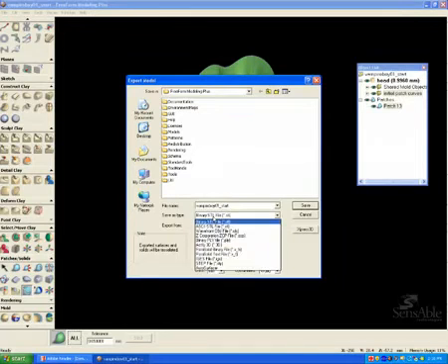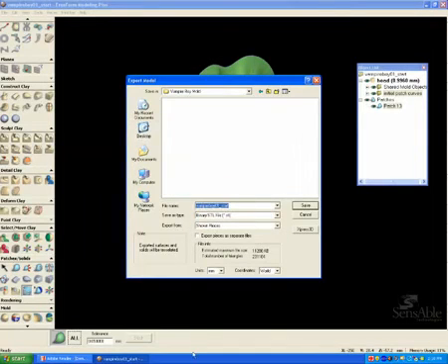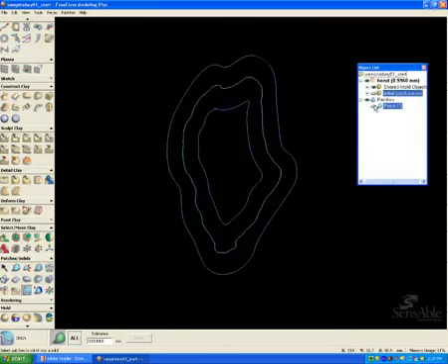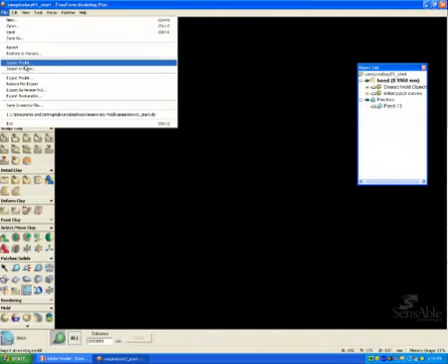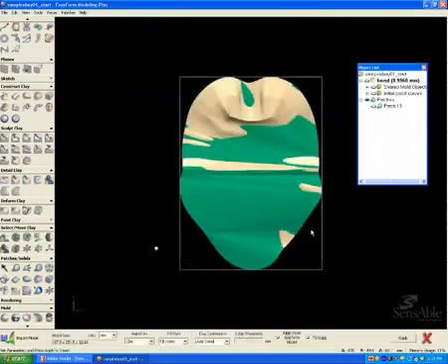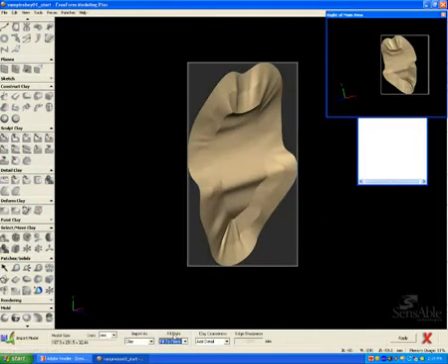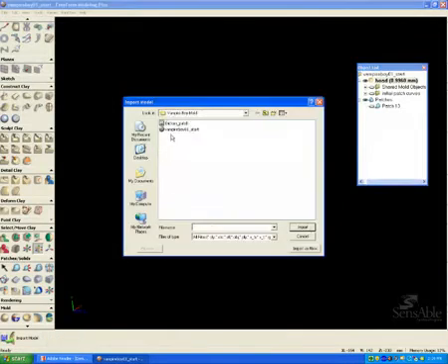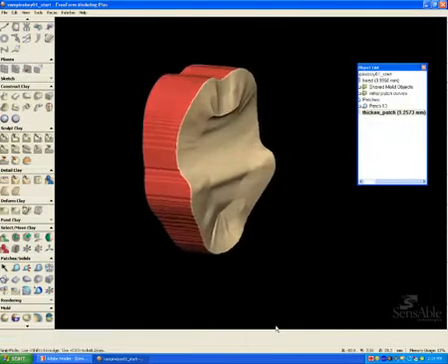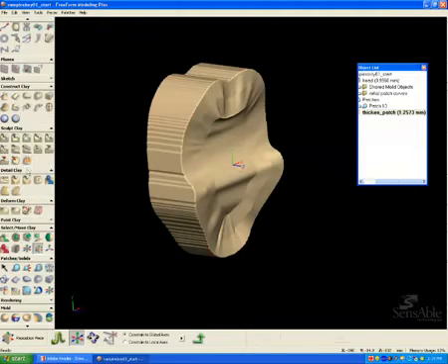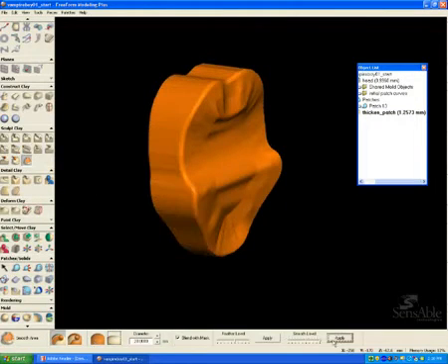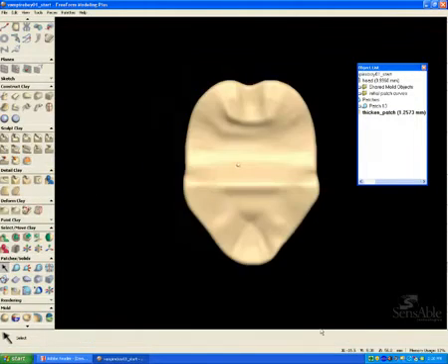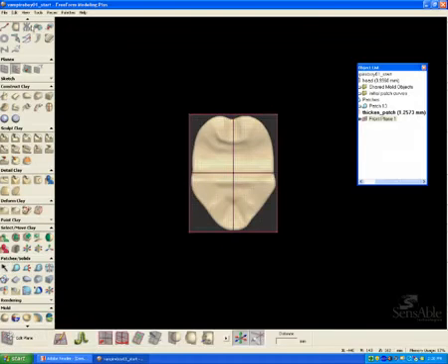So now I'm exporting it out as one binary STL mesh, and then from there I can take that same exact mesh that I just exported and import it right back in. And you can see on the Dynabar I have my import model options, and I want to import this STL mesh and thicken it to plane, so it gives it a thickness of clay right there, and I'm just smoothing it out real quick to give it a better transition.